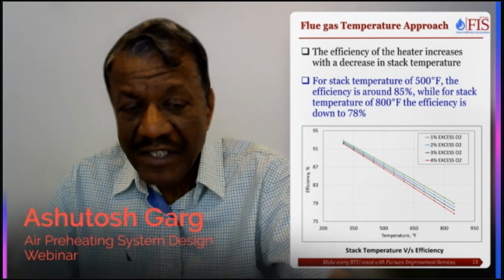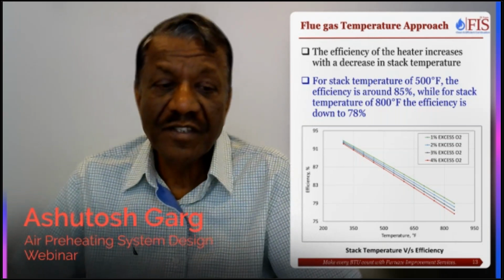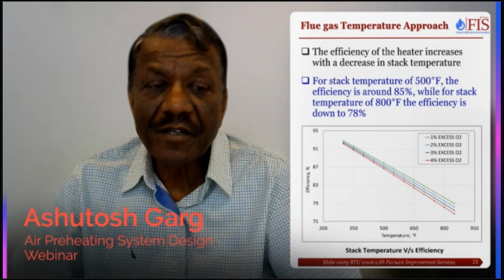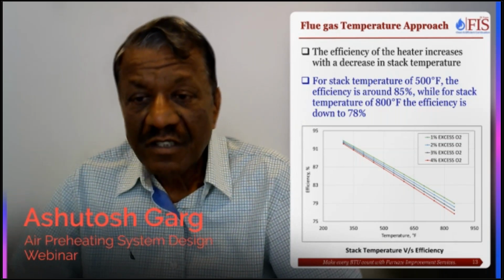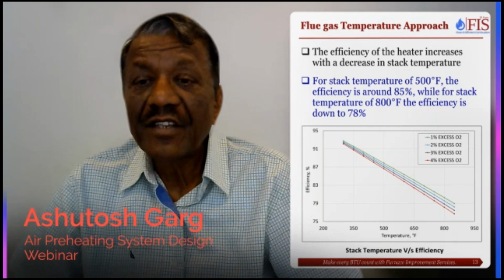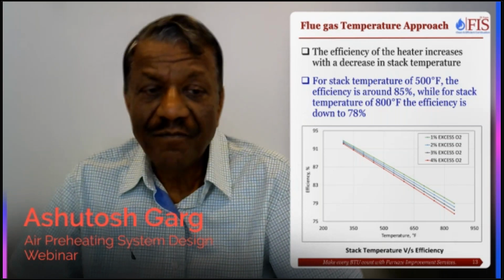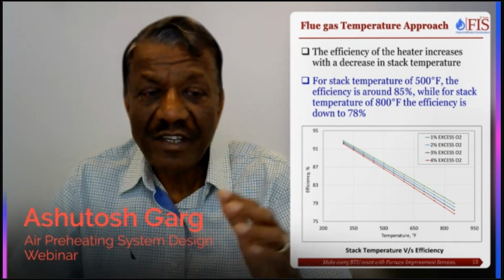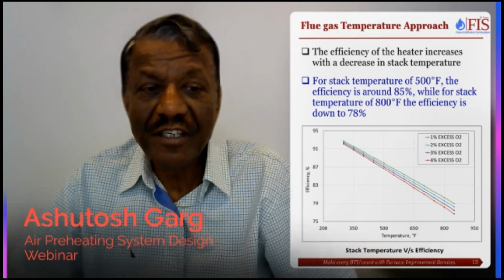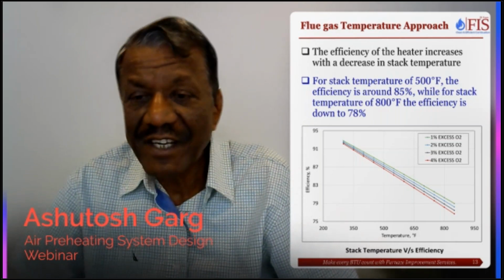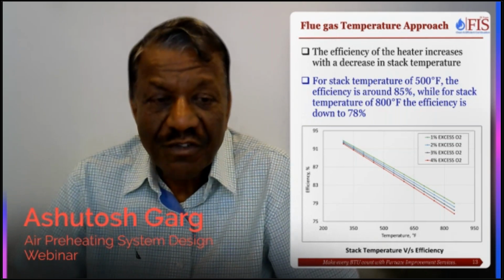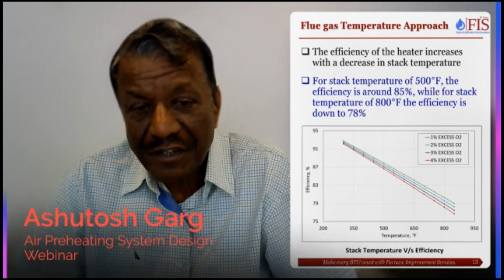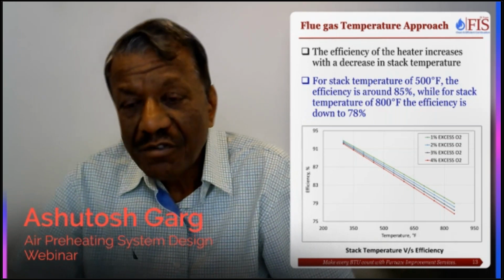My team has done this stack temperature versus thermal efficiency. It does depend on the amount of excess O2 in the flue gases. We are giving you the good numbers over here, 1, 2, 3, 4, which is very, very tight operation; we normally don't see such low excess oxygen in most fired heaters.